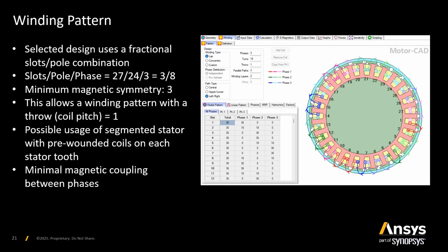So in this specific example, we are dealing with a compact stator lamination ensemble on which the coils have been wound using automatic insertion of the turns per coil. If we look at the distribution, we notice that quite a few coils will be placed and be part of the same phase.